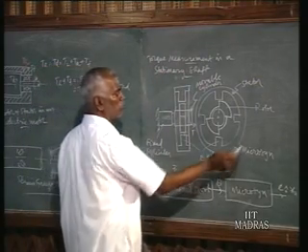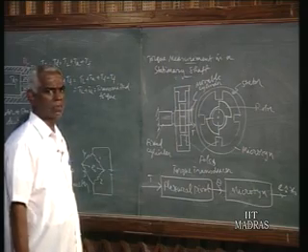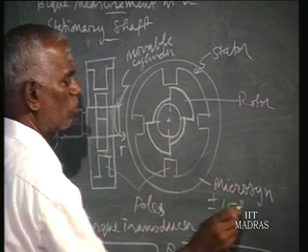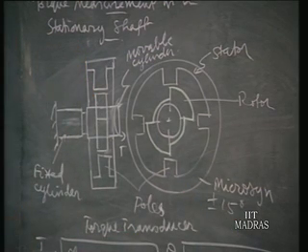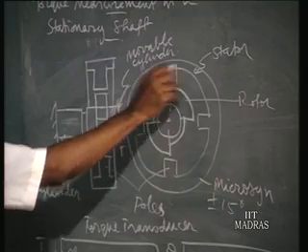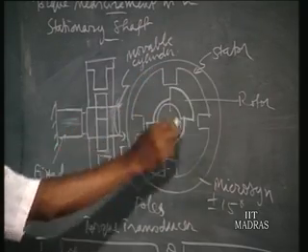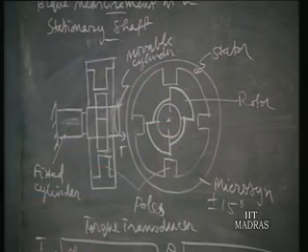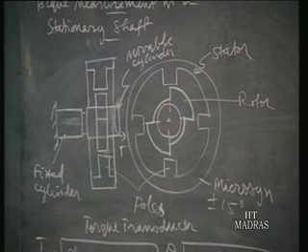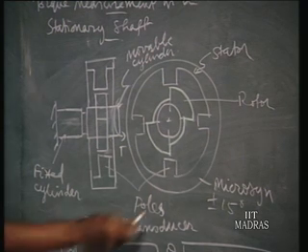For that we can use the microsyn. Microsyn we have learnt already in displacement measurement, and there it can measure plus or minus say 15 degrees of rotation and convert it into proportionate voltage. There we have a rotor, with material distributed against 4 poles, and each pole carries an excitation winding and also a secondary winding. That principle we have learnt already. So microsyn changes the rotation of plus or minus 15 degrees into plus or minus 2.5 volts. So angular rotation to voltage is obtained by microsyn.